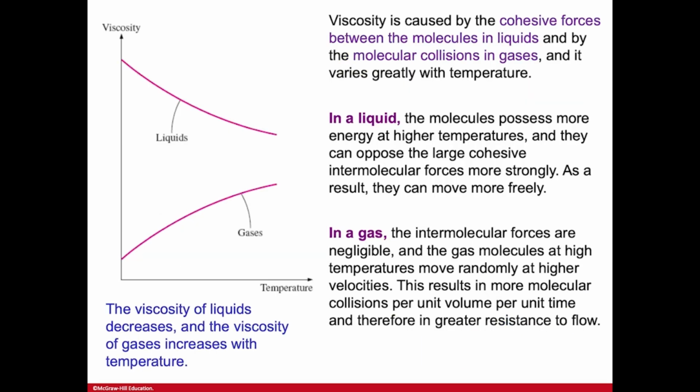So when it comes to viscosity, right, viscosity is temperature dependent, right? So when we talk about honey, or you might have thought about even generic cooking oil that you're looking at, if you heat the cooking oil or if you heat honey, you'll see that it becomes more liquid, or it moves more freely, right? By moving more freely, essentially you're saying the internal resistance of the fluid reduces. That means the viscosity has reduced, right? So essentially for liquids, viscosity decreases with temperature.